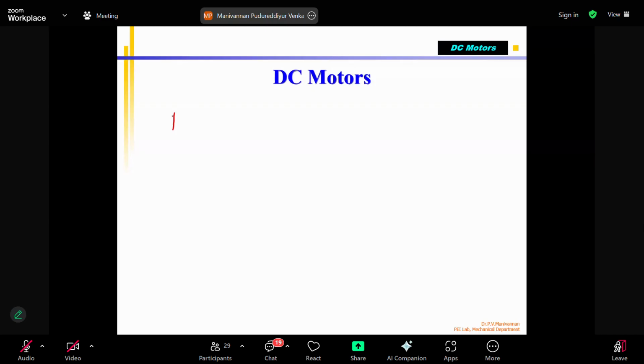Good, nice question, because there are two things. The power consumed by the motor, P rated or motor power rated, is also called continuous. And the other one is called max, or sometimes they put it as peak. Peak power, similarly peak torque, all these things, correct?